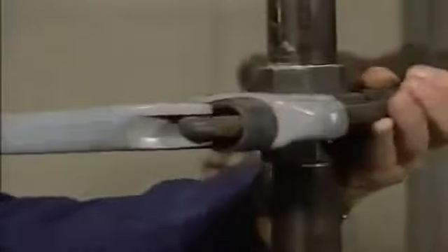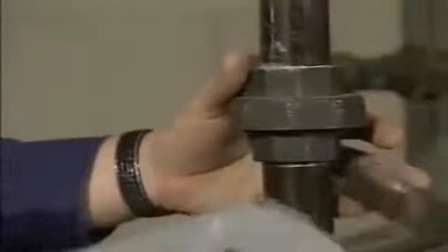On the other hand, threaded joints tend to weaken the pipe wall because the pipe's wall thickness is reduced at the troughs of the threads. Threaded joints are also subject to leaks if they are improperly tightened or sealed.